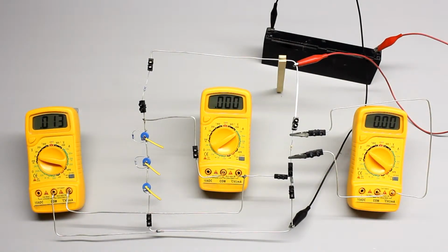Let's start the measurement series by turning all 3 potentiometers to their minimum value. We would now expect a base voltage of 0 volts, but 0.013 volts can be detected. The residual resistance of the potentiometers is one explanation of the detected voltage drop. Another one is given by the electrical properties of a transistor, which will be discovered in course of this video.